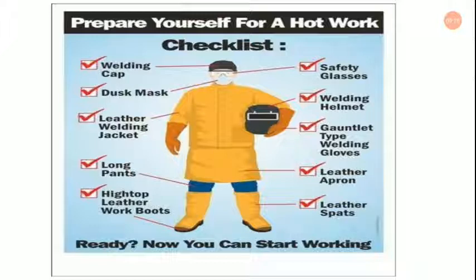Helmet type shields and handheld face shields offer the most complete shading against arc radiation. The shields protect the head, face, ears, and neck from heat, sparks, and flames. As a minimum, use safety glasses with side shields or goggles to protect eyes from flying particles. Side shields on eyewear help protect eyes from flying particles.